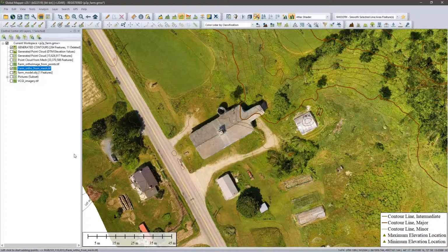One question, going back to the pixels to point process itself: you had referenced being able to determine the height at the start point as a default value. Is that the height of the ground at the first image, or the height of the drone at the first image, or what is that height? Yeah, it's the height of the ground at the first image. So if you have loaded terrain, it will look at the X and Y position of the drone, and it will derive that terrain height at that location. So it's an automated tool. Yep, and so it's going to basically adjust the entire point cloud so that that location aligns with that height. Okay.